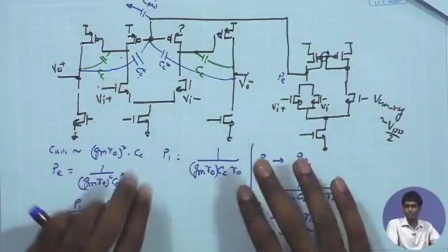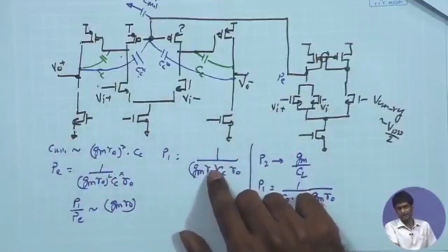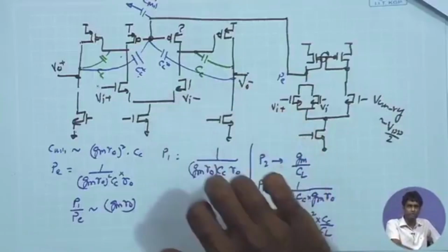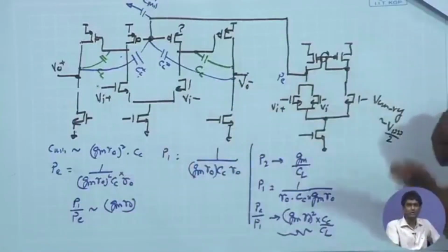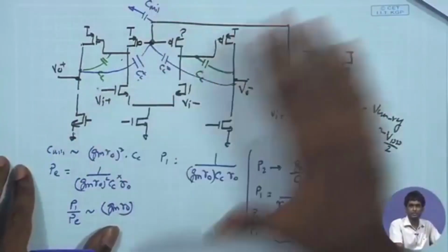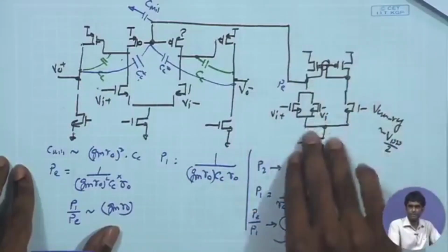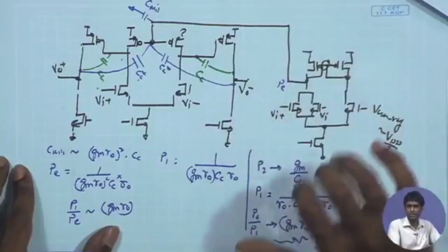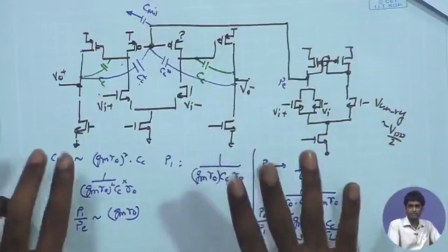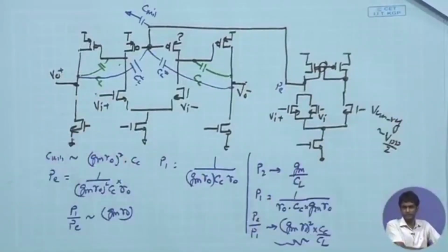What are the pros and cons? So all this analysis we try to do will give you a better idea of the design choices that we are making. So, even if that's not a good choice in some condition, in some other conditions it may become a good choice, where your area constraint is possibly smaller and you want to have common mode having much lesser current, so that the gain of the stage is large and you are having a large RO anyway. So, in those cases you may end up using it. So, if you are simulating it and trying to see what is the disadvantage, you should be at least aware of this trade off.